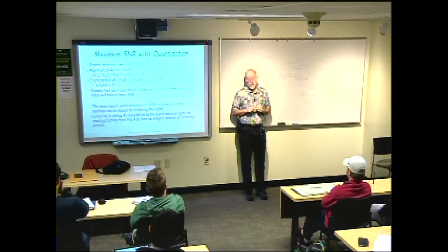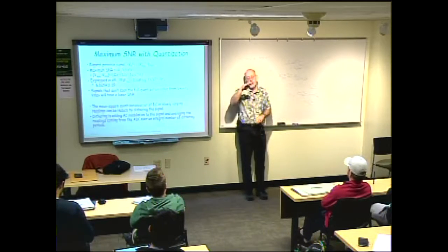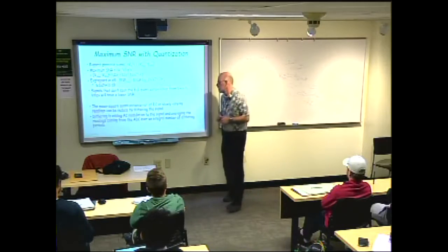So if you have some teeny little signal that's only taking up a centimeter or so of that 10-centimeter display, you're actually not using the last couple of bits of the display. So whenever you're using a digitizing oscilloscope and you're pulling data off of it to analyze, if you want the best quality data, you need to fill the display with the signal. All right?